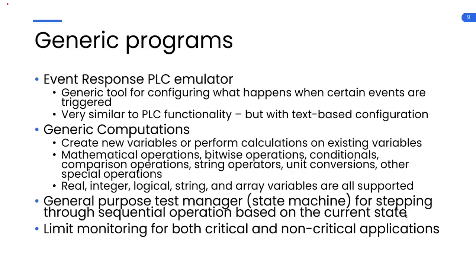We've also got switch statements. So another common application for this is you might tell an emissions bench to zero or span, and it might send an integer value back that could be a few different things. And so you'll have a mode to send the message, a mode to receive it, and then a mode to look at that integer value and then use a switch statement, or a case statement if you're familiar with case statements, to say if it's equal to 1, then do this. If it's equal to 4, do that. If it's equal to 99, do this other thing. So we've got that capability. This is a very powerful and configurable program. It's kind of crucial to what CyFlex is, this GP test, general purpose test manager.